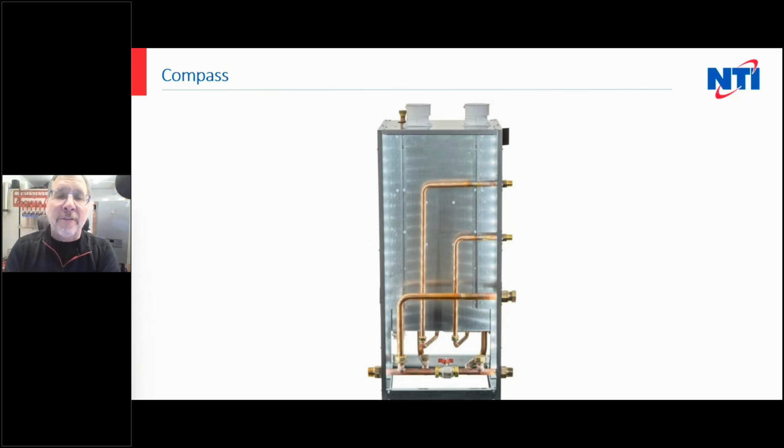This thing has everything built into it that you've always wanted. It's got the low loss header. It's got the changeable supplies and returns. It can pump your indirect if it's a heat only unit. It can give you up to 5 gallons a minute on 199 on domestic for a plate heat exchanger. Your gas can be on either side. We did everything we possibly could think of and then more.